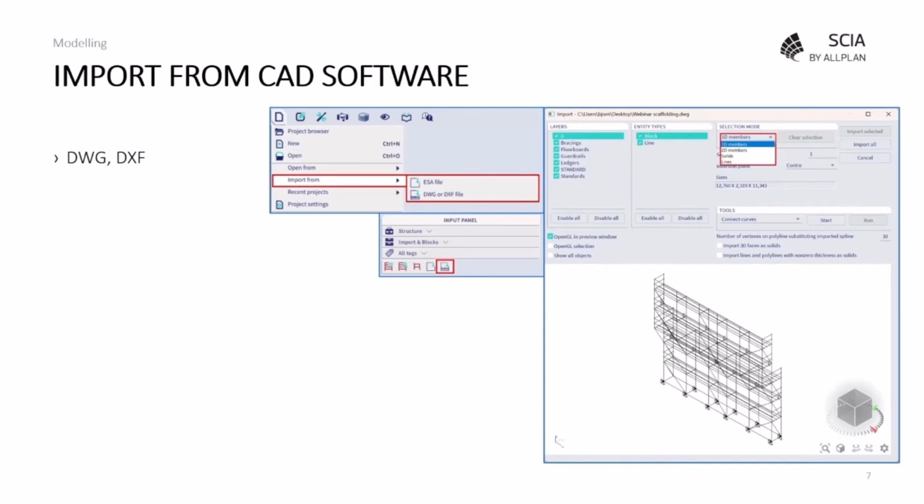It is recommended to use your system lines or your access lines of the structure, because if you connect those properly in the nodes, you will already have an analytical model that you could immediately use for calculation.